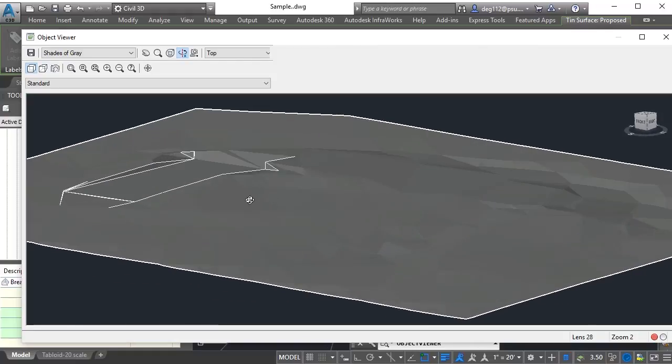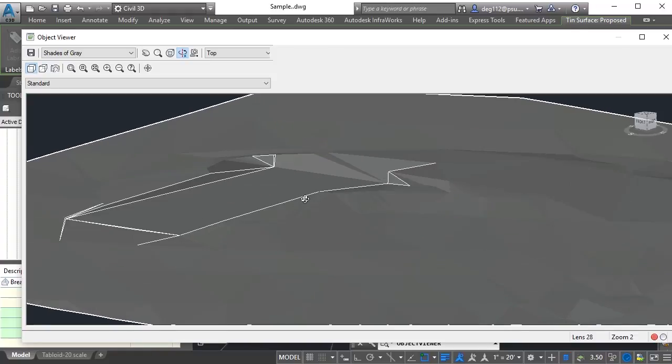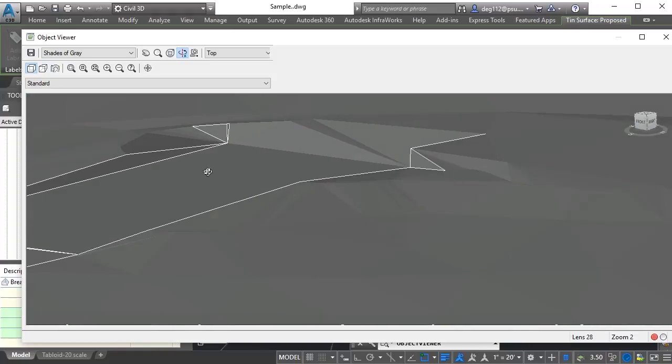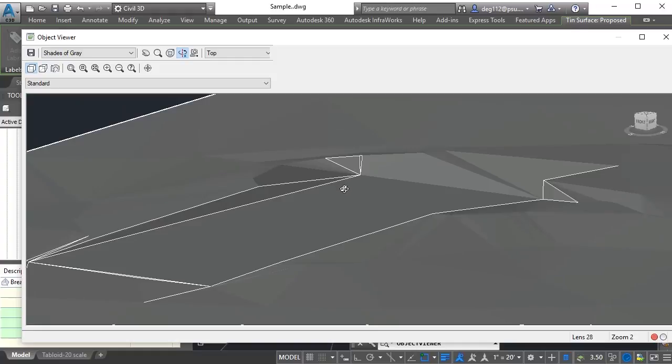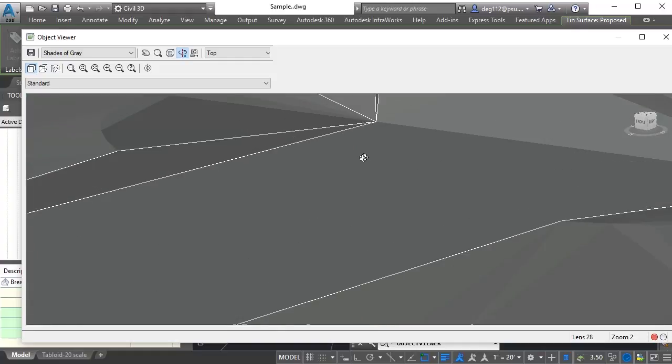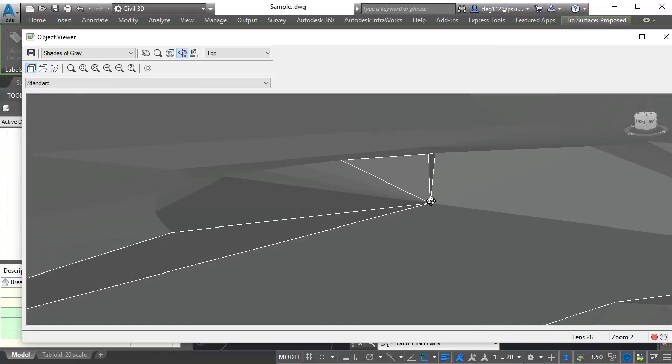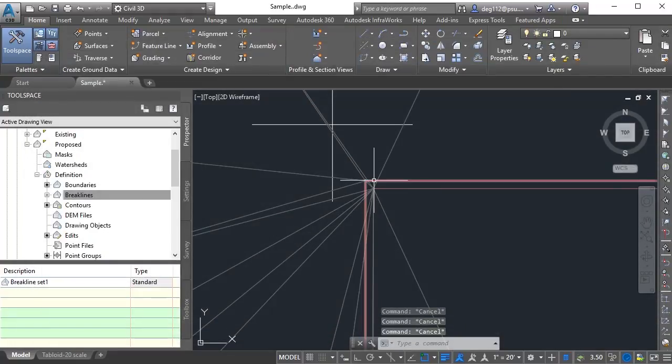You can see inside there, hit shift on, I don't really have a defined wall. This is not a defined wall. It's kind of going down to that low point. You can see how it's going right down to that low point in here. That's not what I want. I want this to actually hold a wall up and a wall around the side. So what I need to do is actually create an elevation information around this edge.